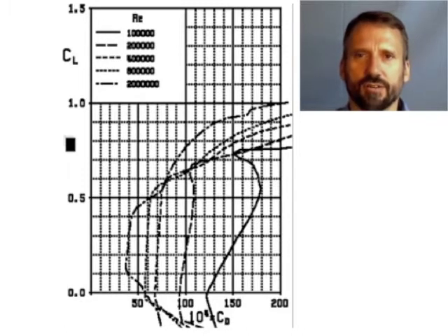One thing to notice here is how much compression of data there is in the form of this catalog. Reynolds number, coefficient of lift, and coefficient of drag are each functions of 4 or 5 different variables. So there's a lot of information here, which enables us to compare airfoils of very different sizes under very different conditions and still use the same table, the same airfoil, the same trade-off curve.